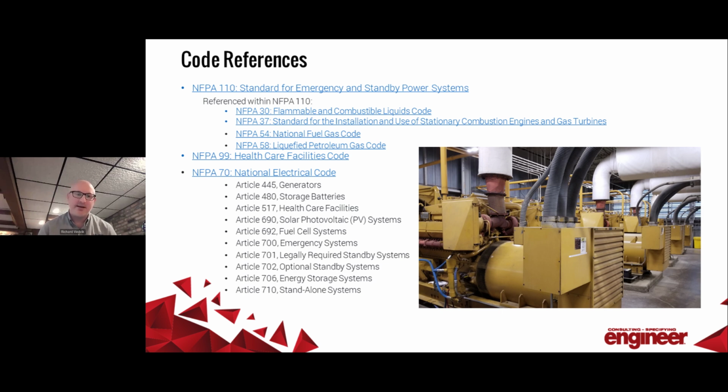But you'll notice that throughout this presentation, we're going to be talking about other sections of code. I've listed some here, not to read them to you, but to remind you that you're not just looking at 110 and calling it a day. You're also going to look at every applicable section based on the type of fuel you're using. And of course, you're going to have to reference NFPA 70, and there's a variety of articles within there that are going to be more specific to those different types.